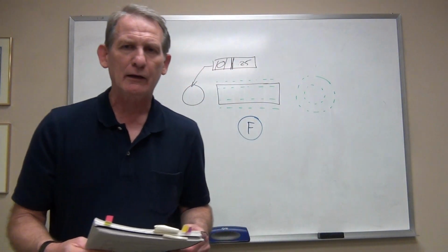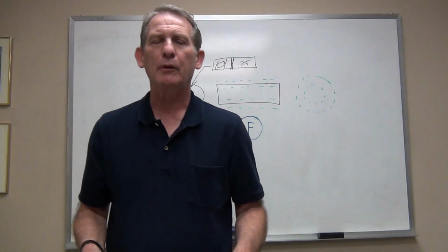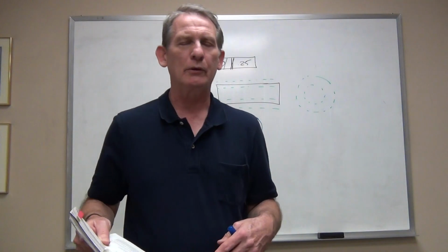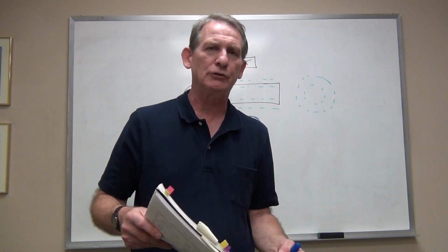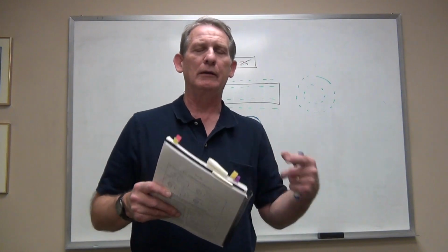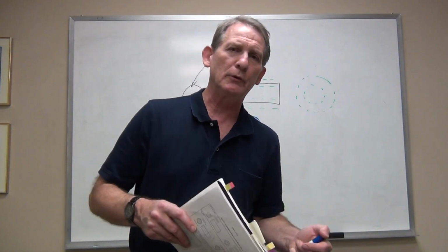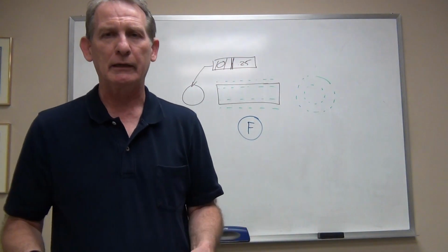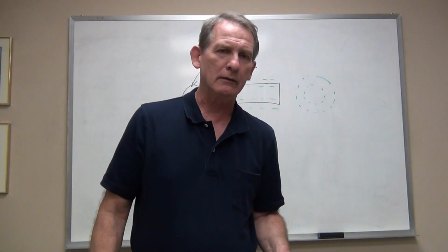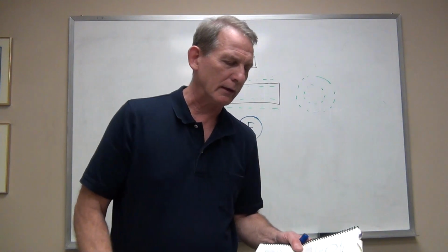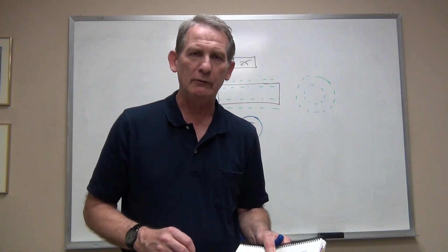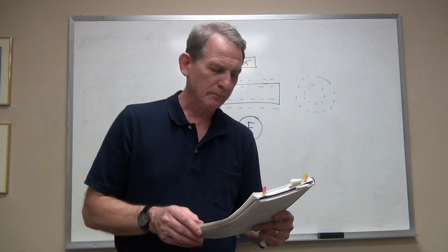Free state tells you that that requirement applies in the free state. In other words, in order to measure this, you don't have to put it on a jig, put it back in a chuck or in a collet, squeeze it back round and then measure it. You can actually do the measurements, do the averaging in the free state. So that free state modifier in the tolerance area tells you when you do the evaluation or how you do it.